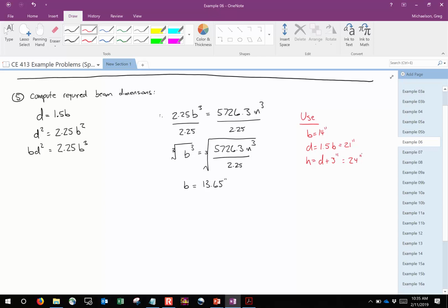Well, that's a reasonable discussion. Let me also say this. Incredibly rarely would I ever round down. I'd probably always round up, because think of what you're talking about. We're talking about the required size of a beam to safely resist these loads. So even if the number was something like 13.2, I'd always round up to the nearest inch, because I always want more beam to be conservative.